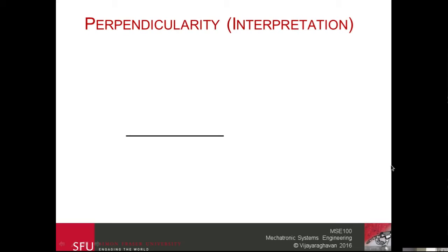So what does it actually mean? Essentially, I've defined a basis line, which is kind of an imaginary, virtual average, and then I'm going to draw two vertical lines, which refer to my bound. If I give a 0.01 tolerance, that means this distance is going to be 0.01, and my side surface can lie anywhere within those two bounds, but it needs to be completely within that bound that I've shown.